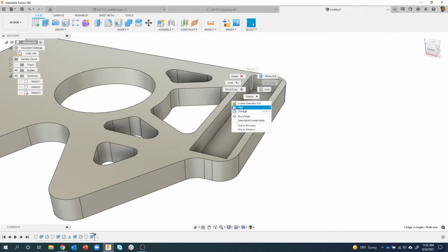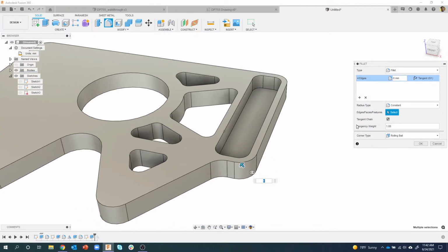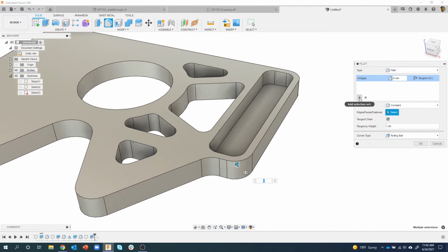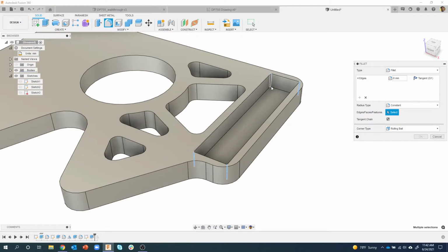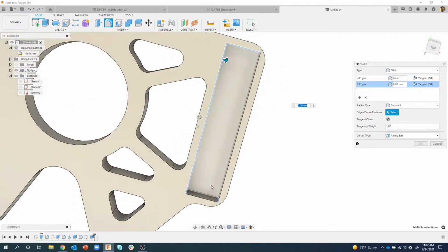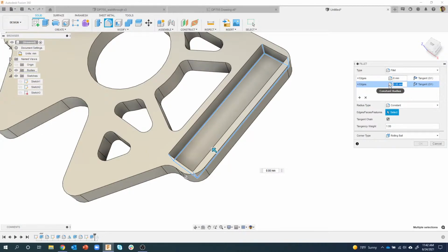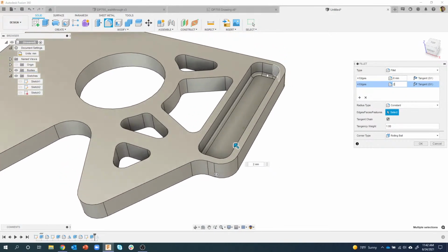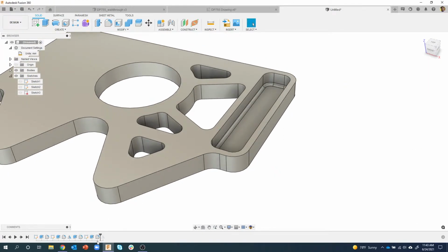Let's go ahead and fillet this pocket. So I think these are radius 6 according to the drawing. So there's that guy. Now, if I were to come in and add a selection set, I could, but notice that these fillets go away, so I have to manually select all 4 of these edges. And I even have to rotate potentially or whatever. But then I could come in and say, okay, that is a radius of 2, and it'll do all of them in one fillet feature.